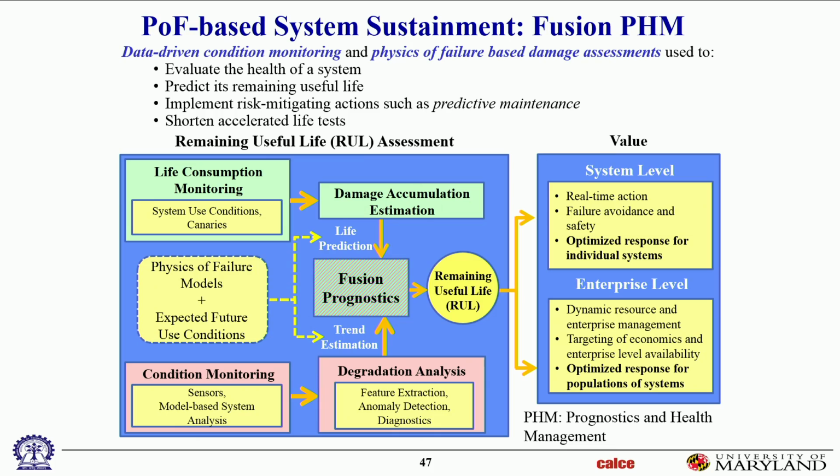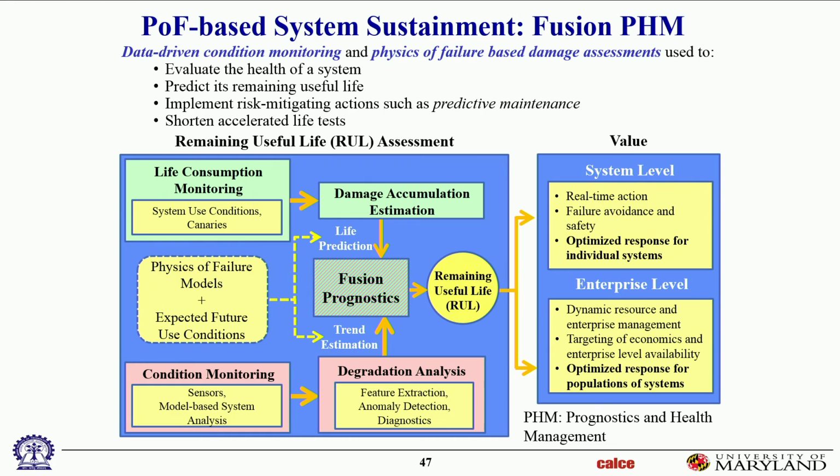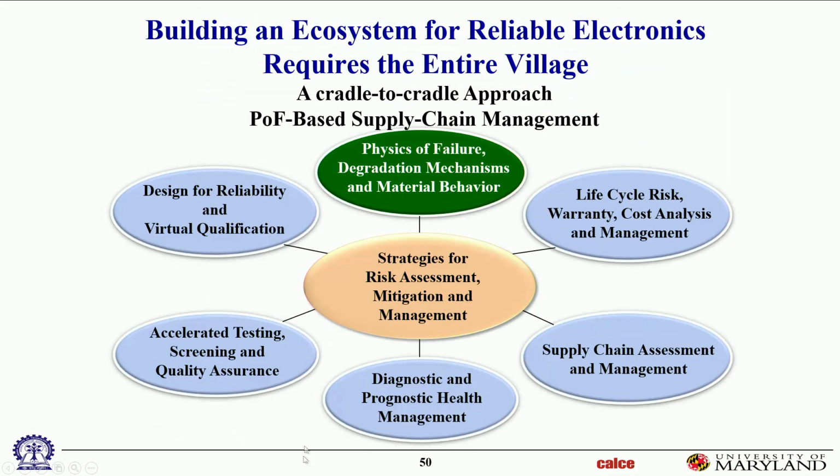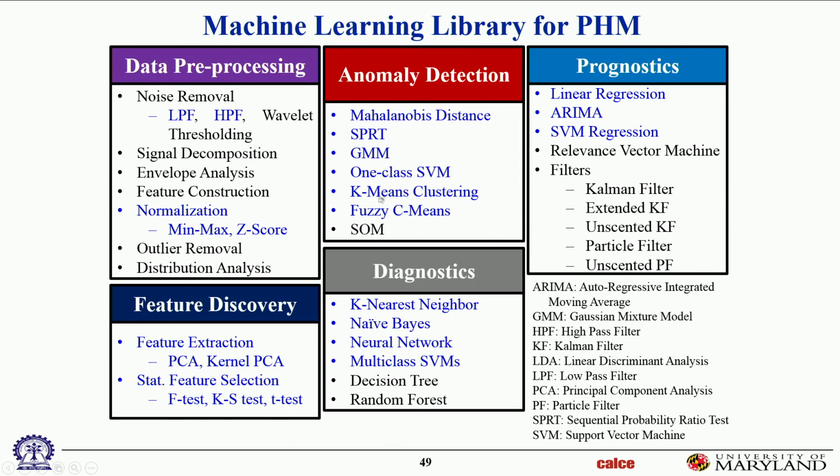So that way you have early warning, and you design a canary for 50% life, 80% life. The canary fails, you know you've used up 80% of the life of the product. So my job is to use physics of failure principles to intentionally design weakened structures to act as canaries. But the rest of it is very sophisticated, a lot of data analytics and so on, a lot of computer scientists working in this with our teams. I'm not going to get into that, okay? Okay, so that's all PHM. Here are some of the data analytics tool sets.